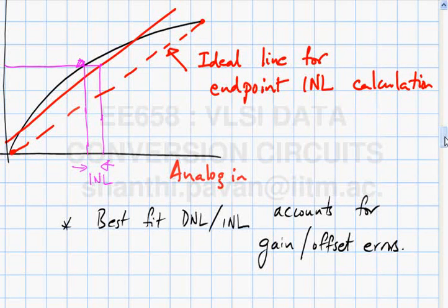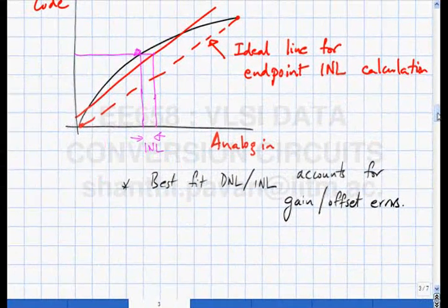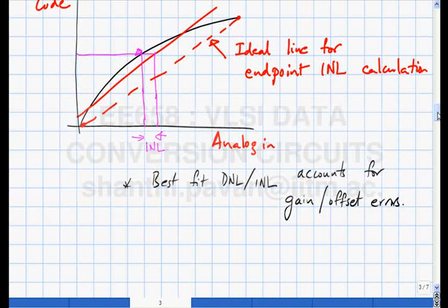There will be applications where, for example, in video, on your video monitors, any signal processing for video will be quite tolerant of INL, a lot of INL, but will be very intolerant of having DNL. Why? If you have observed, the human eye is very good at capturing contrasts.